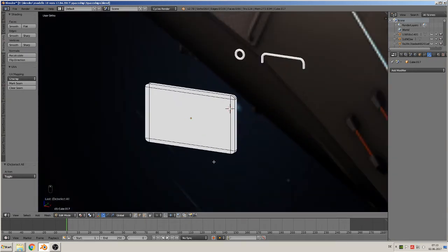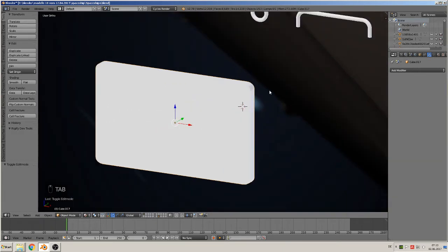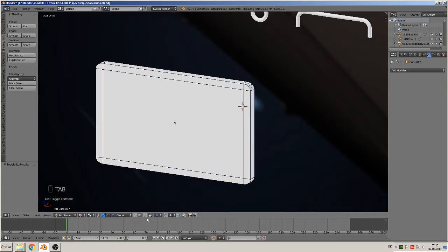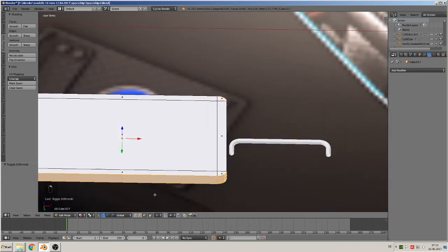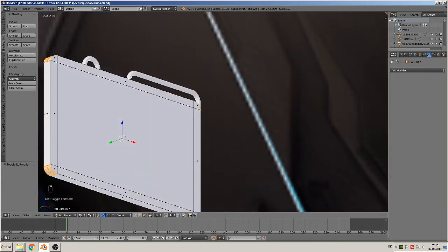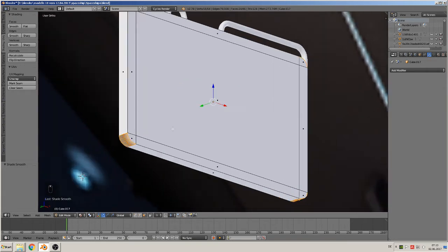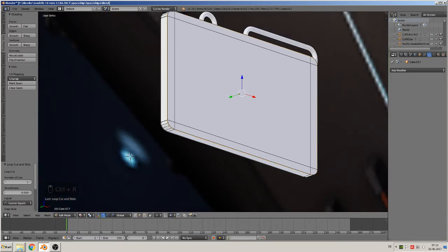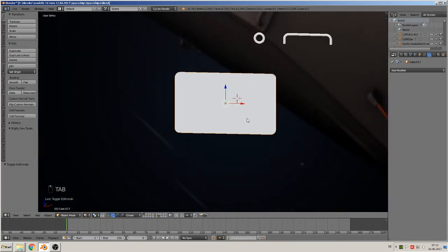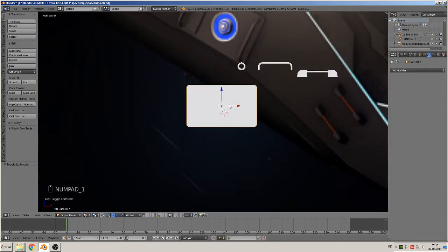So we can give them a smooth here on the places where it is round. We can mark all that and leave these parts out. And the rest should not be flat, it should be smoothed. See what happens, we get shading errors. For that we need a loop on both sides, and the shading error is in the small part between, and nobody sees that. Good. We have that one.